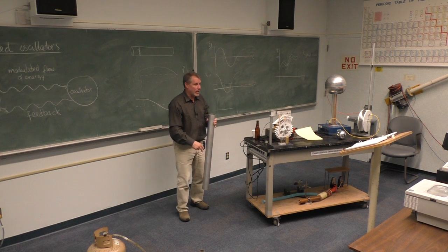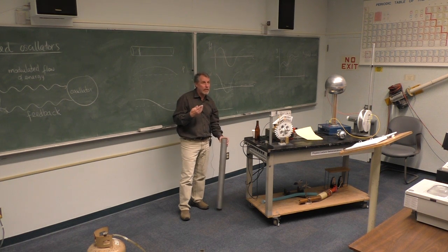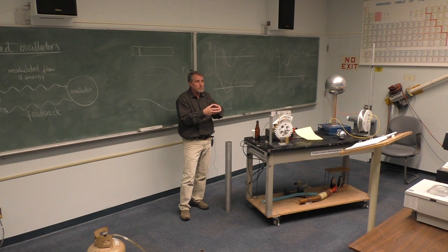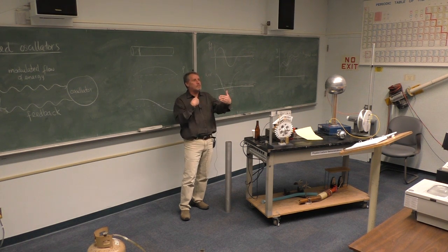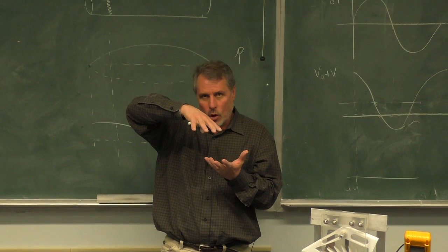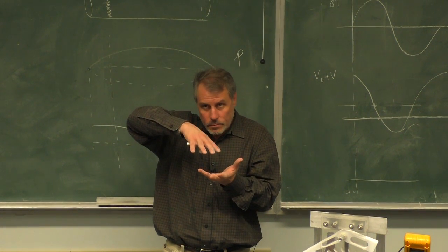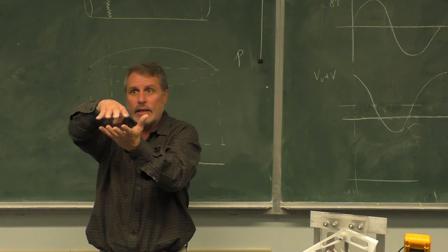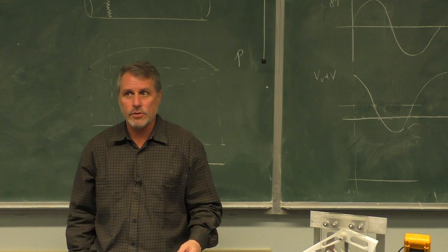Okay, so it's again another example of a maintained oscillator. Where is the energy coming from? The heat on the metallic mesh. That's where the energy is coming from. Is it oscillating? No, it's not oscillating. It's a DC source. But the way the energy is being modulated is by having that convection flow that is rising, that is bringing gas particles through the metallic mesh and dumping the heat that they get during the compression cycle.